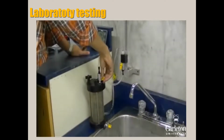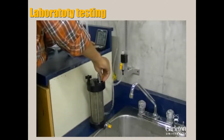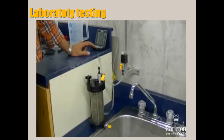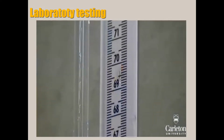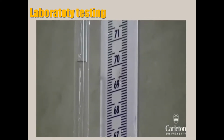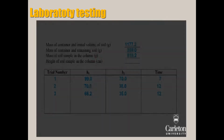For the first test, use a stopwatch to record the time it takes for the water to drop a certain distance. Start the stopwatch and open the valve simultaneously. Wait for the water level in the pipe to drop a given distance. Close the valve and stop the stopwatch simultaneously when the new level is reached. Record both levels of water, as well as the time in seconds it took for the water level to drop. If the water level is too low, add more. Repeat this test 2 more times for 3 readings in all.